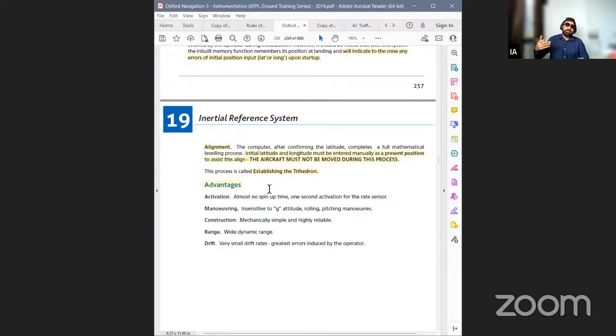So IRS is an advanced navigation system that gives us a lot of data that is fed to my autopilot, my manual flying, and gives me a lot of information which has become a sort of primary information for navigators. So all your attitude direction indicators and everything else are standby instruments in one way or the other. And they also take in data from the IRS. IRS uses RLG, ring laser gyro.